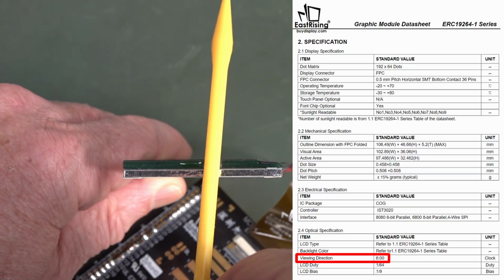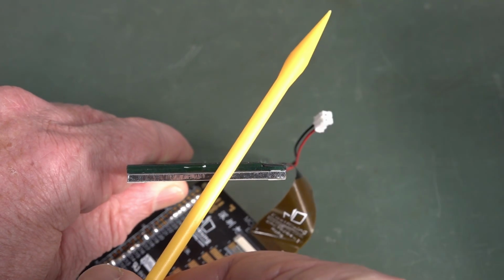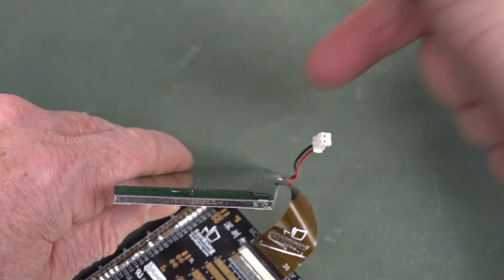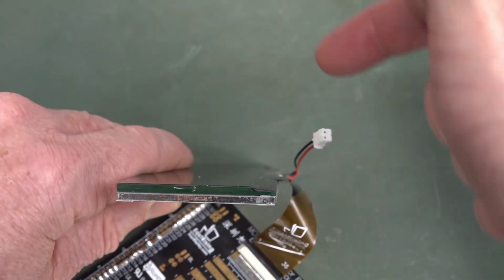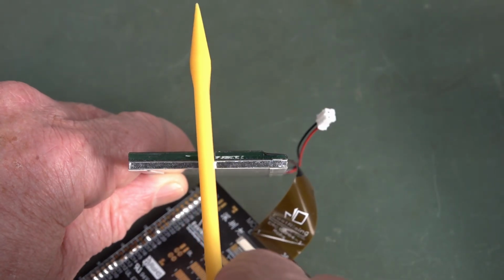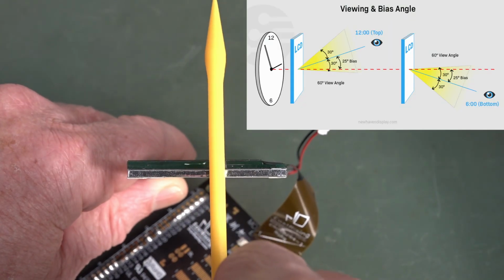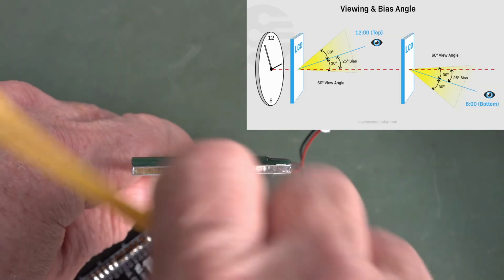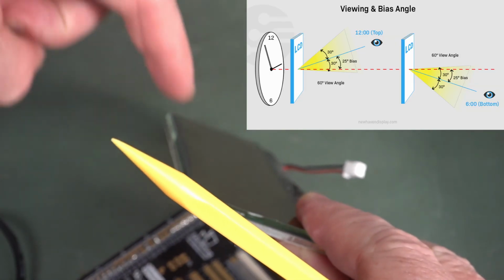So it's designed to be viewed from a lower angle like that. If your eyes are over here, you're looking up at the screen. So that's called a 6 o'clock bias or viewing angle. And if you get a 12 o'clock one, it's actually over here like this, so you're looking down on the LCD.